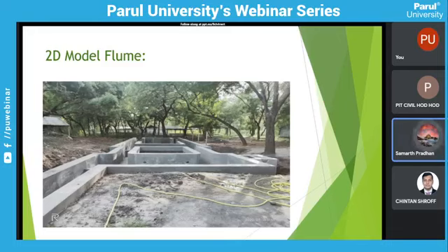Then the most important thing is the standing wave flume. In fluid mechanics, you might have studied various types of flume. We are adopting the standing wave flume. It is the measuring device from which we give the discharge. Suppose you want to run the model on 10% discharge. The standing wave flume is the measuring device, and just adjoining it you can see the chamber is also there.